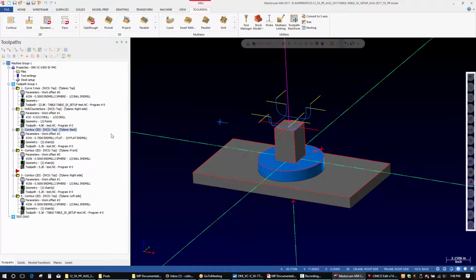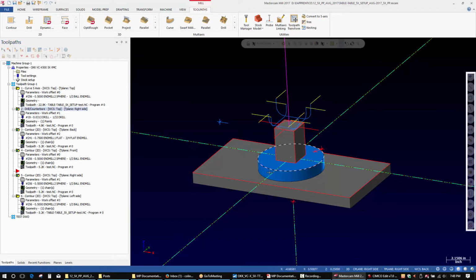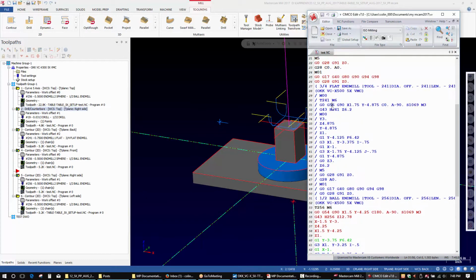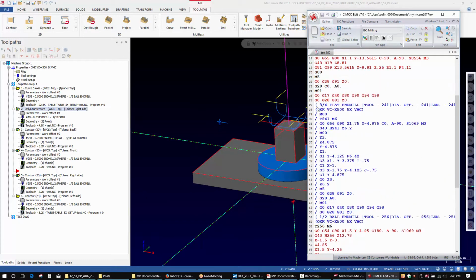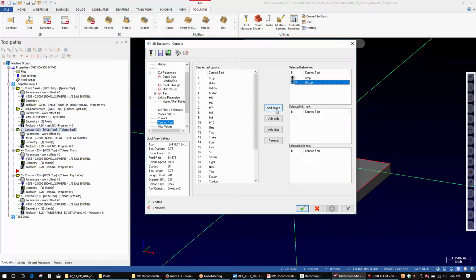But we now grab those ops again, repost them, and we're able to essentially skip the entire operation if we throw the block delete switch on the machine. If we did it at the with stage instead of at before.